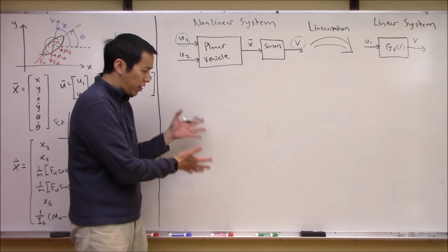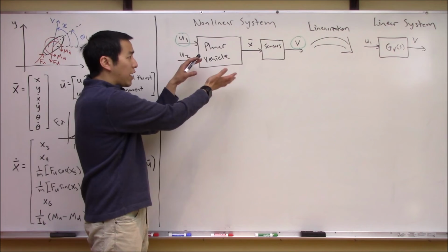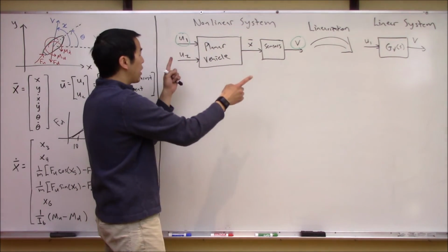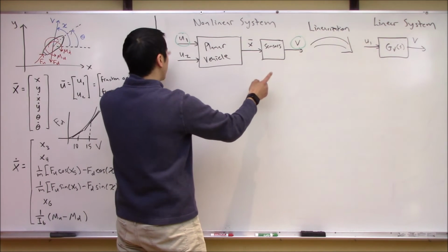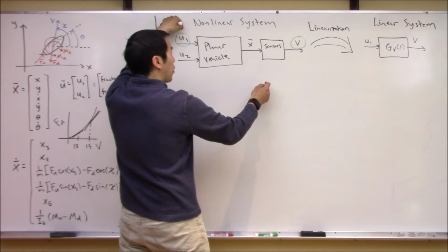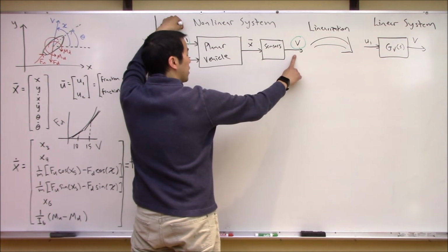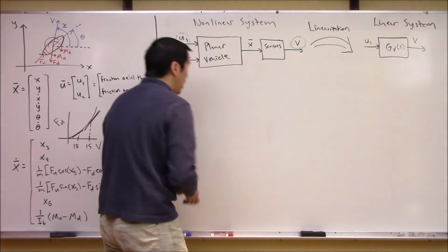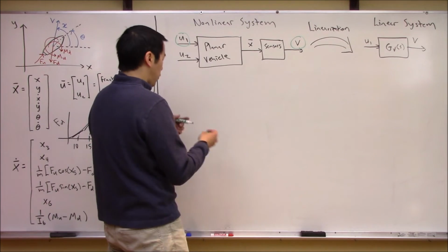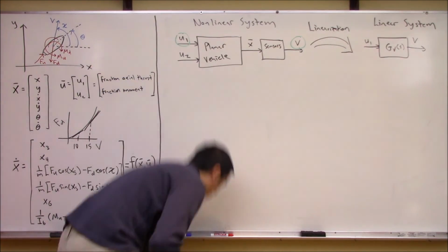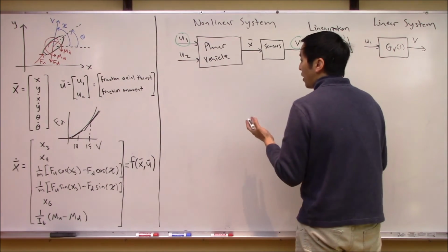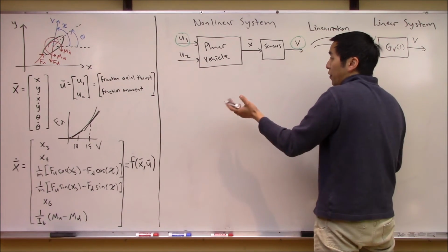So I've just gone ahead and erased the board and moved our diagram up to the top where we'd have a little bit more room. This is what we were looking at earlier, right? Getting the linear system between axial, throttle, and velocity at a given operating point. Well, we can actually just add in more inputs and more outputs. So for example, what if we said, I want to understand how does the axial input force affect the heading angle of the vehicle, or theta.